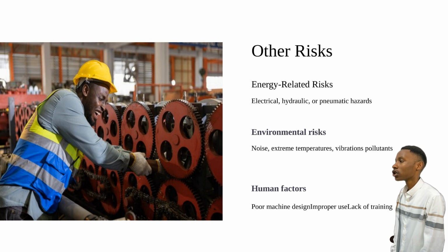Mechanical work also exposes operators to other dangers. Energy-related risks, electricity, hydraulics, and pneumatics can cause severe accidents if mishandled. Environmental risks, noise, extreme temperatures, vibrations, and exposure to pollutants can affect worker health. Human factors. Poor system design, improper equipment use, or lack of training increase the risk of accidents. To prevent these hazards, it is essential to follow proper procedures, use appropriate protective gear, and ensure adequate training.